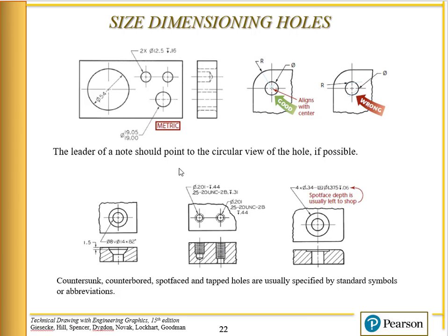Hello. This is about dimensioning holes. A leader should point to the center view of the hole if possible. What we're talking about here is we have a radius, and the leader for the radius points to the center of the radius.